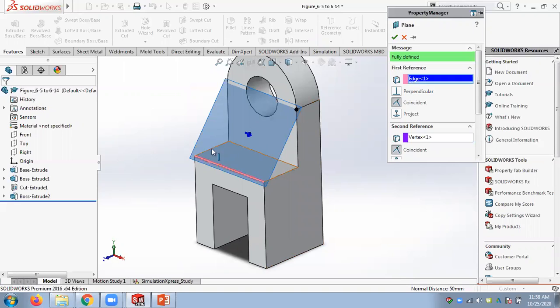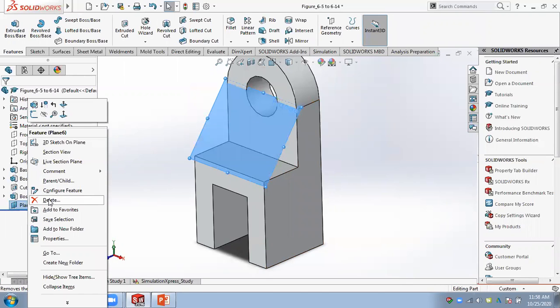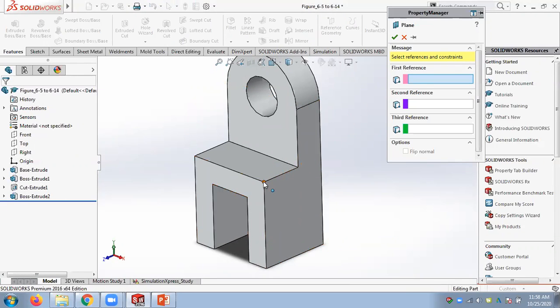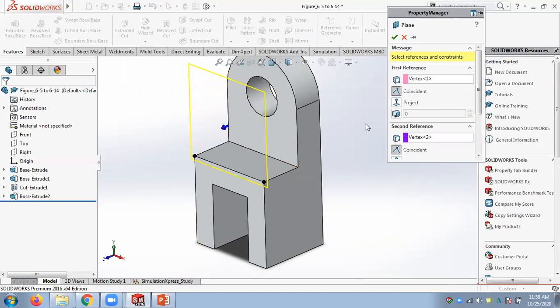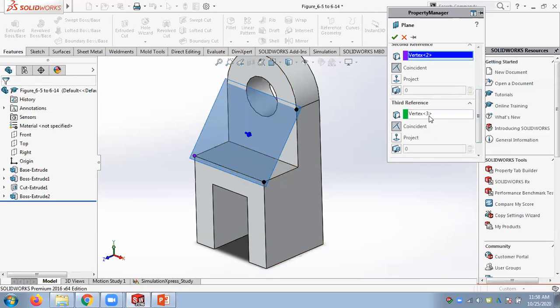So I selected the edge. Edge has a lot of points, and one point from this place. So we can have a plane like this. Suppose you select 3 points. The worst case is selecting this point and this point, still floating, and this. So the worst case is you need to have 3 points to create a fully defined plane: vertex 1, vertex 2 and vertex 3.